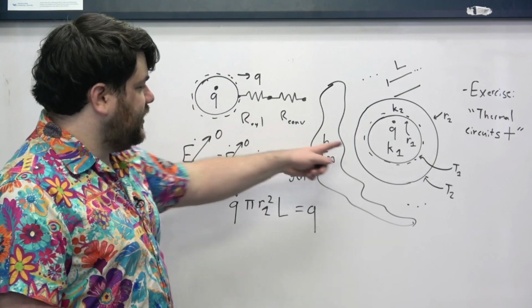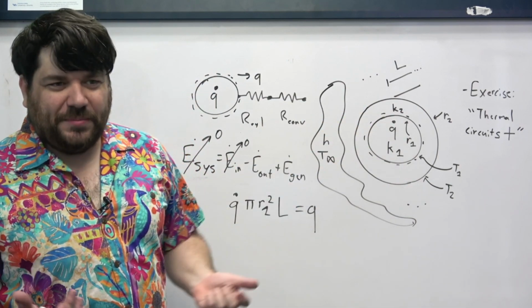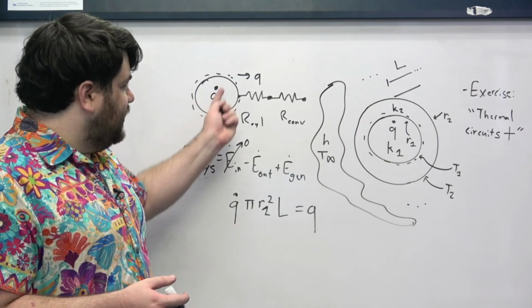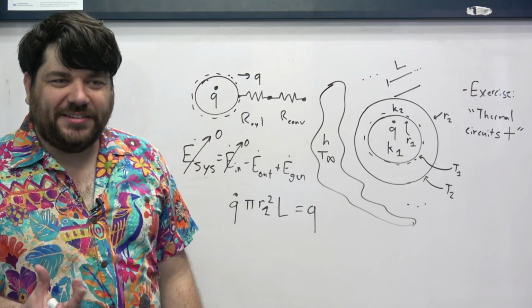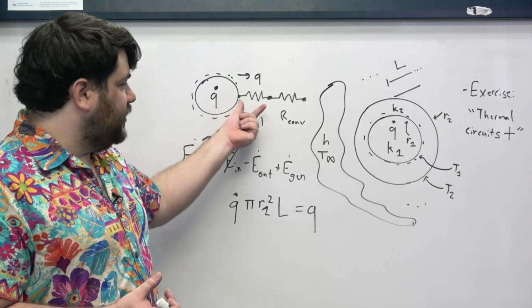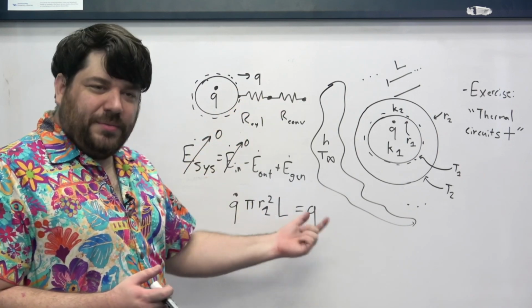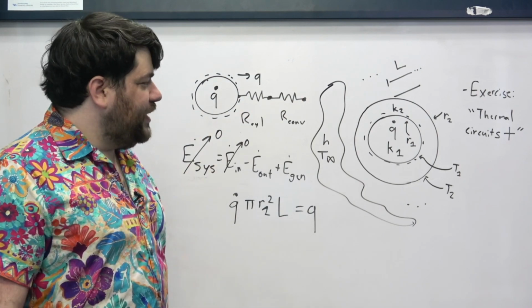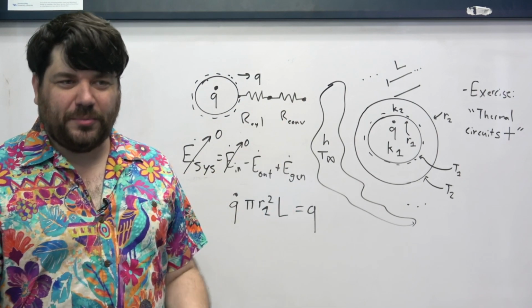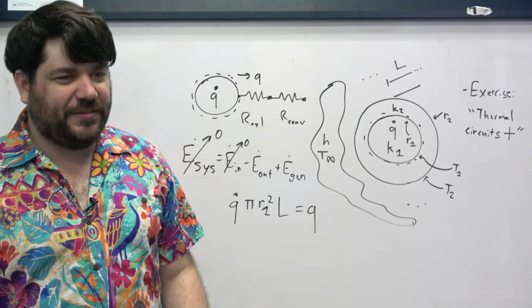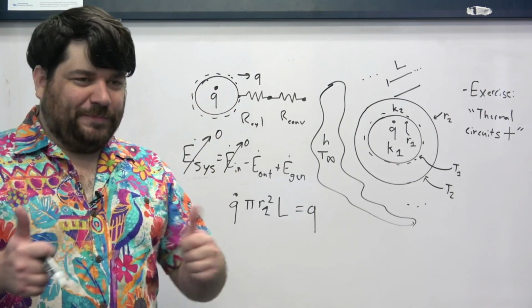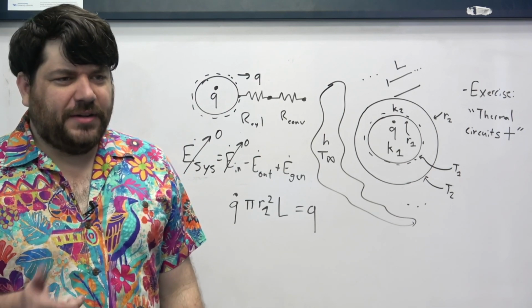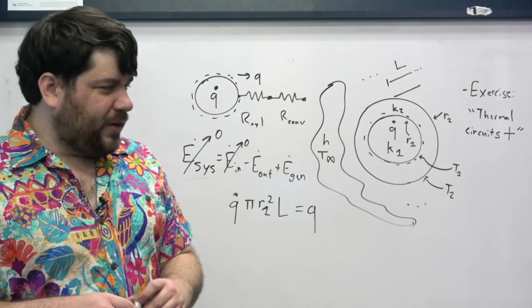If you're trying to find a temperature at a boundary or something like that, you don't actually have to care about what's going on in this heating cylinder, because all of the information about the thermal circuit has been pulled from this relationship. And so I could figure out, for example, what the temperature over here or over here is by doing a thermal circuit analysis and forgetting this ever existed. Okay? So, great.